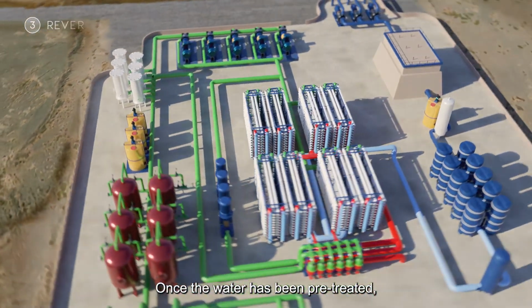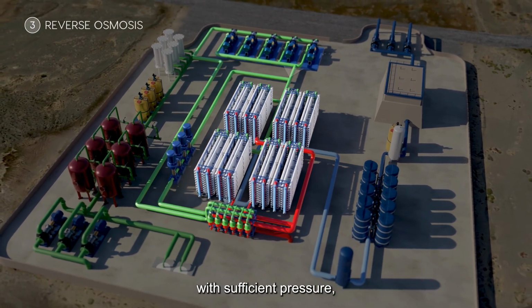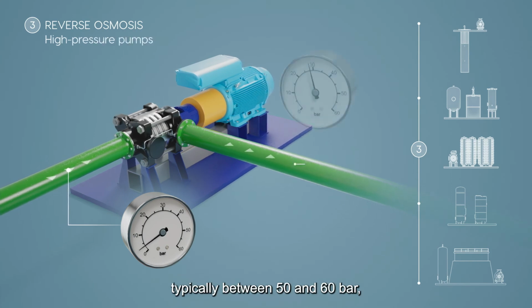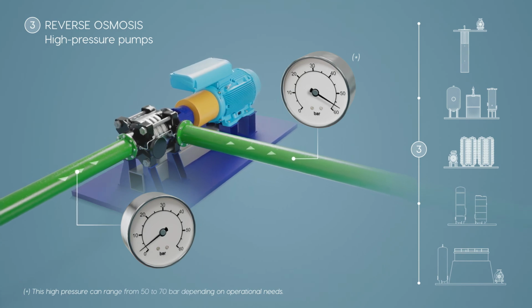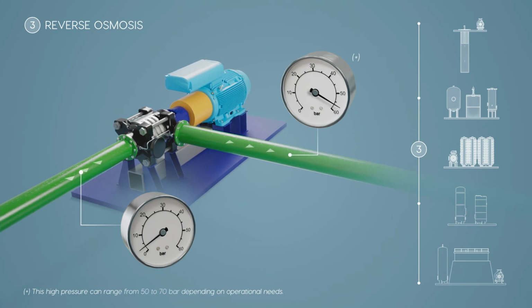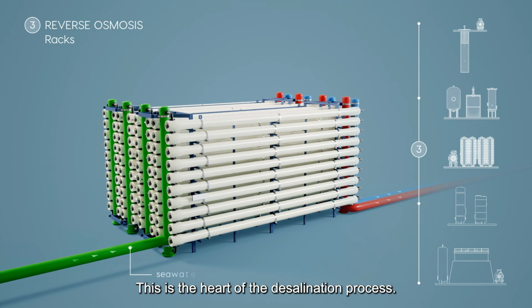Once the water has been pre-treated, it needs to be pumped into the membrane rack with sufficient pressure, typically between 50 and 60 bar, for the reverse osmosis process to be carried out efficiently. A high-pressure pump is used to achieve this. This is the heart of the desalination process.